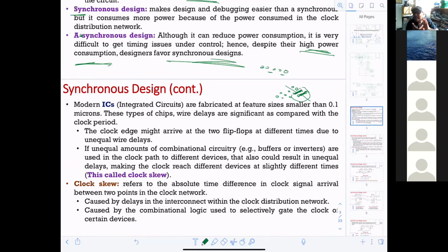So it will build kind of a capacitor, but it doesn't really exist. That's why they call it a parasitic capacitor. It's like a stray, something virtual. And that will cause something called delay. Why delay? Because there is leakage. If I'm dictating 5 volts in this area, but because of this it came to 4.3, then the decision will be delayed a little bit because I have to compensate it to be 5. Does that make sense? That's basically what is written in front of you.